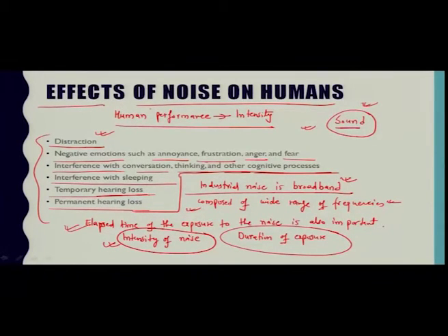Sound intensity is measured using a sound level meter, which is basically a sound pressure meter that converts the reading to decibels. Most meters allow the user to set one of several different scales when taking a sound pressure measurement.